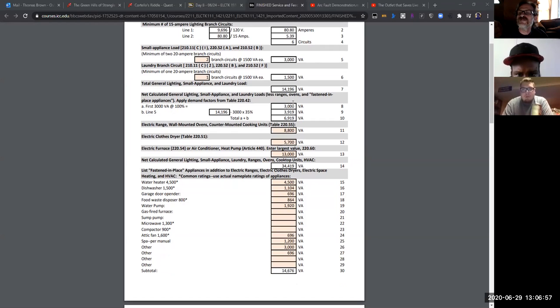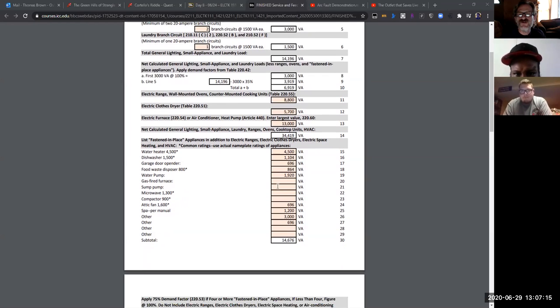And remember, on page 4 there are instructions for each step to help you out with any of the math and formulas. Each one of these, you're just going through and plugging in the formulas, adding them, subtracting them as you need to, and sizing each one. Of course, you can't put stuff in there that isn't in the house. In this case, there wasn't a sump pump listed. But wherever there is stuff listed, you come up with all these appliances together and an overall appliance number.